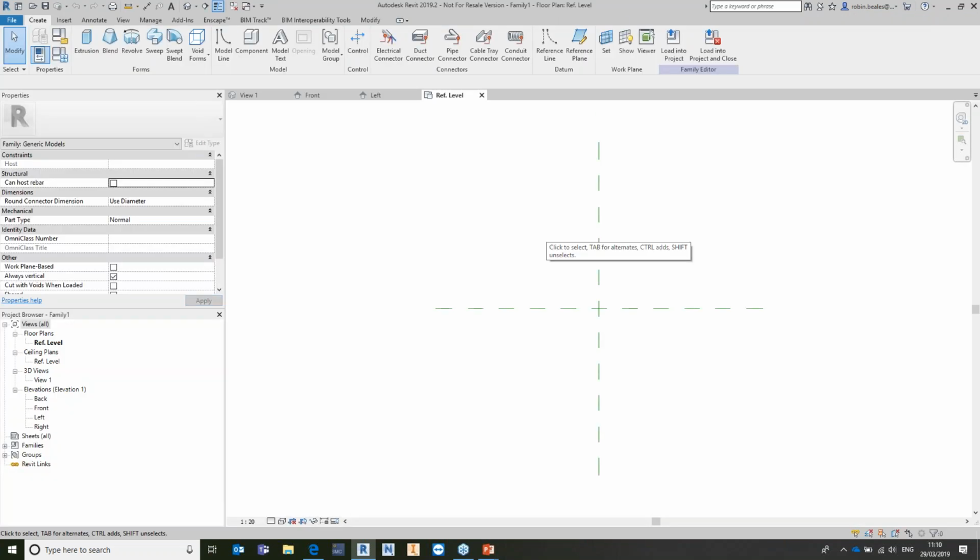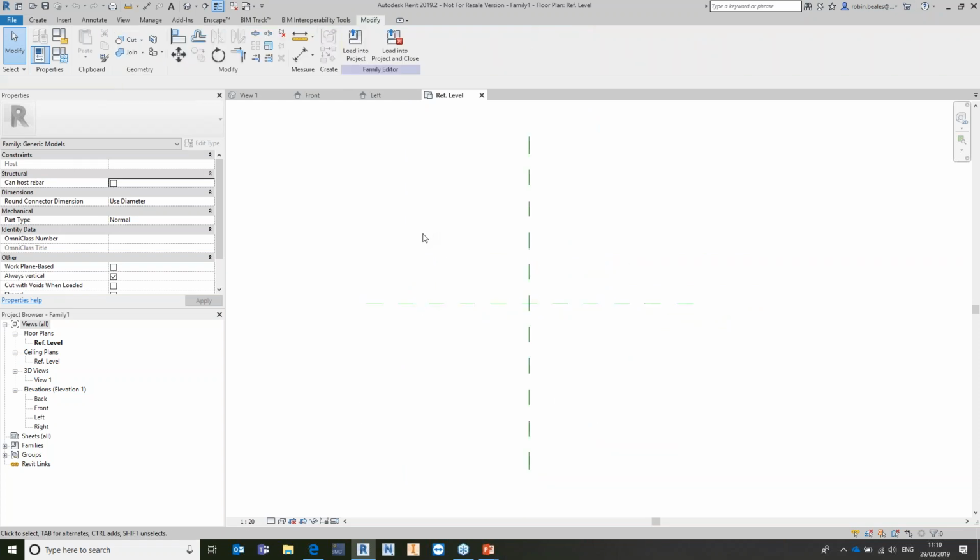because what we'd want to do from a BIM perspective is draw representative geometry and then add information against that. And again, just to give you an understanding of how this works, it's very similar really to drawing inside of any other piece of CAD software. We have a workspace. These are just center lines. Think of them like work planes inside of Inventor. Okay, they work exactly the same way.